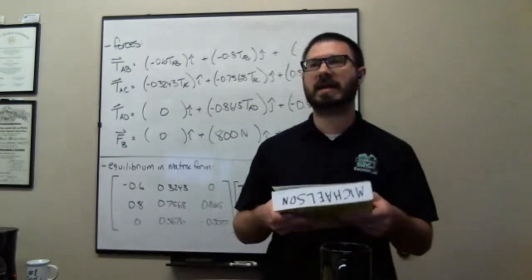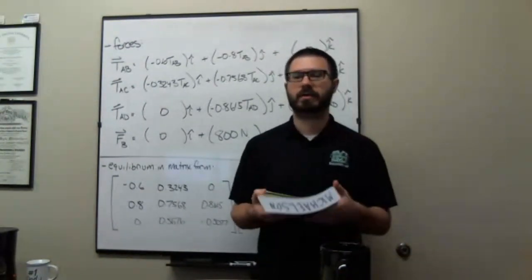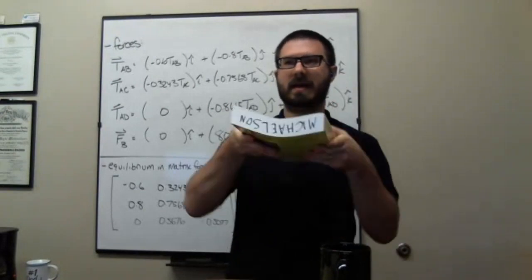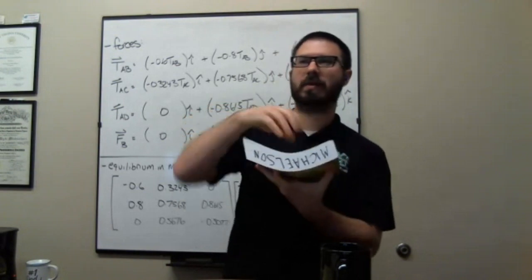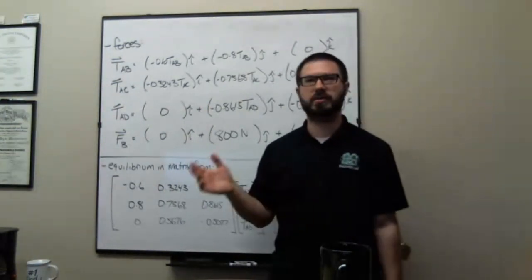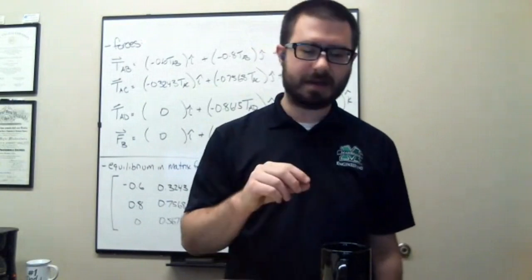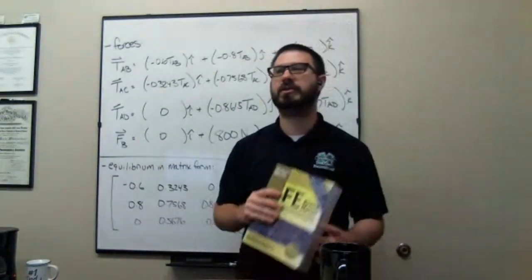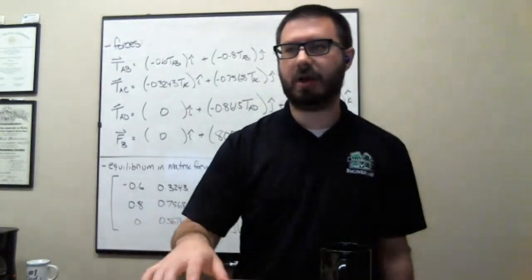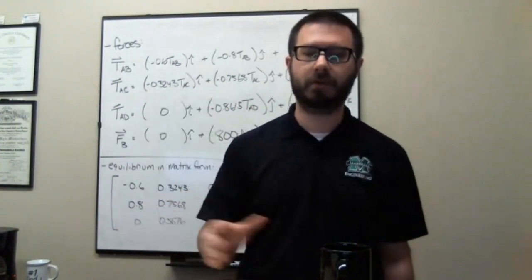What that's talking about is taking a section and bending it. Now, when you bend a beam, usually the beam is supported, maybe something like this, and you've got a load placed on top of it. By now, from what we've done in structural analysis and all the classes you've had with me, you know that when you do that, not only do you generate a bending moment, but you generate a shear.